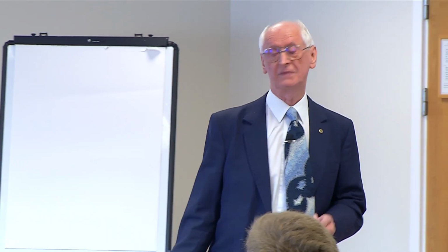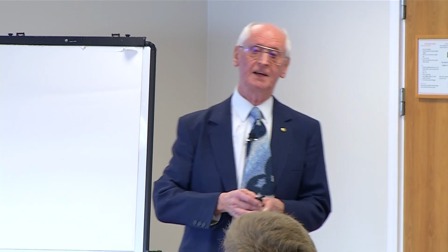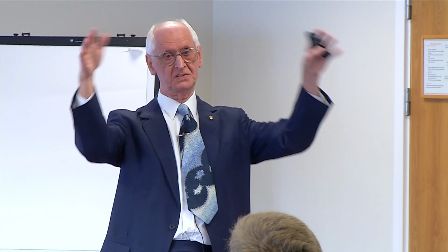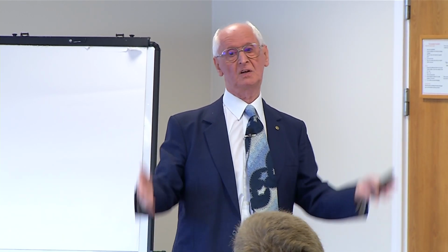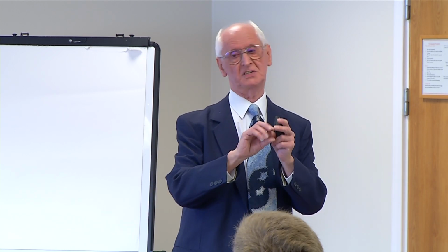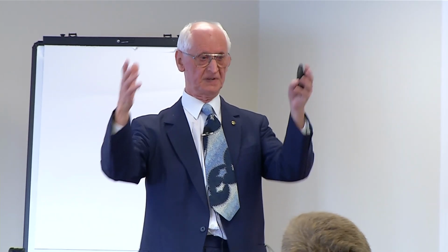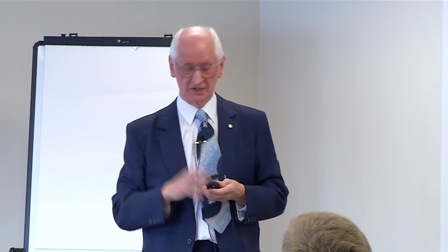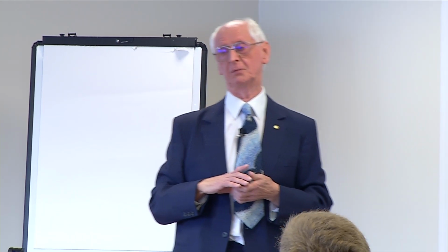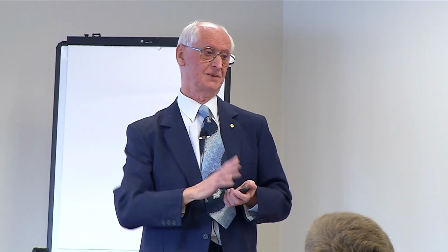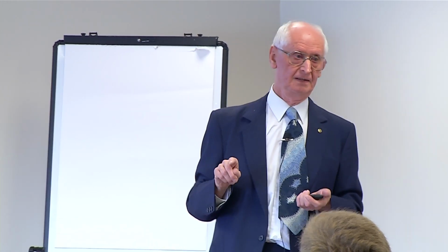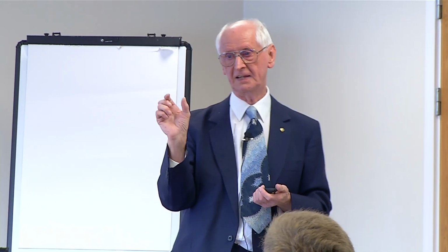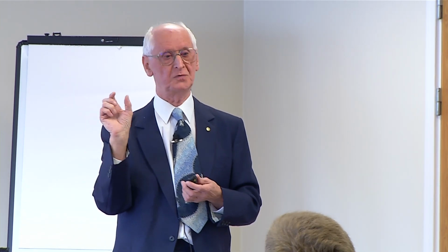People do, and I will give you a good example. There was a large warehouse type building. You've all seen them, the B&Q type buildings. They have metal cladding on the outside, which is fixed to an iron steel sheeting rail fixed to the columns. They thought, oh, this is really good, we can use coated aluminium cladding because that will last a long time, which in one sense is true. But they then fixed it with a little self-drilling, self-tapping screw made of stainless steel.